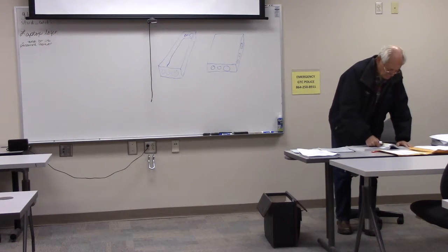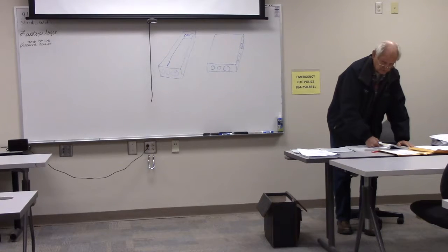Where angle or U-pulls are made, the distance between each raceway entry inside the box and the opposite wall of the box shall not be less than 6 times the trade diameter or metric designator of the largest raceway in a row. So what's the largest raceway in that? 3 inch. All right. This distance shall be increased for additional entries by the amount of the sum of the trade diameters, metric designator of all other raceway entries in the same row on the same wall of the box.